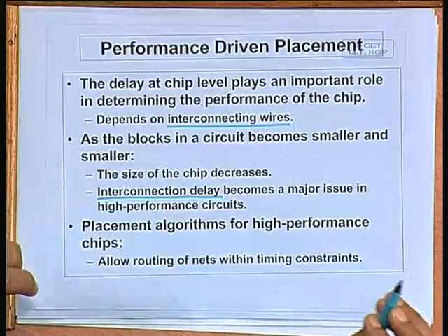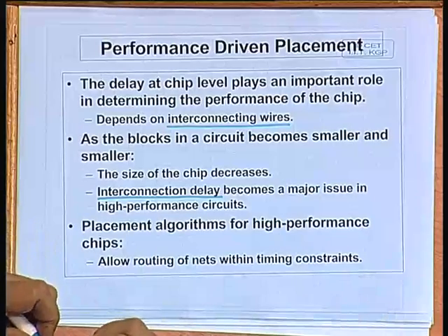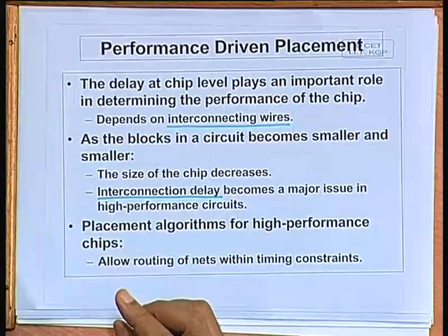Sir, heat generated we did not take into account. Heat generated we did not take into account, that is of course an issue. See, normally what happens is that many placement tools, like you can look at some of the tools which are available commercially, while doing a placement will not take care of the heat, but there is a tool using which you can observe a heat profile of the total floor area. You will find that some portion of the chip will get more heated than the other. Then through manual intervention you can modify the placement.